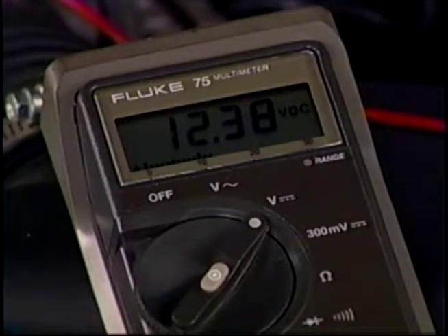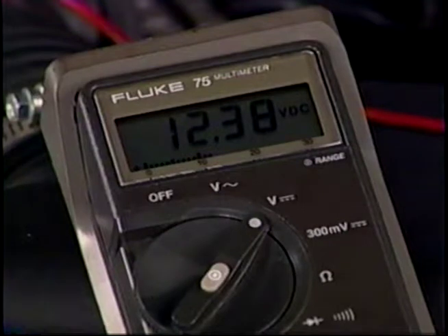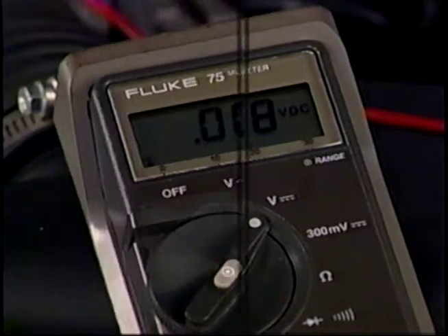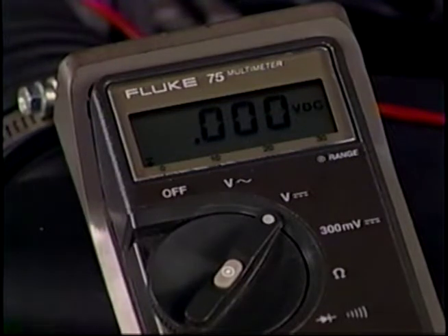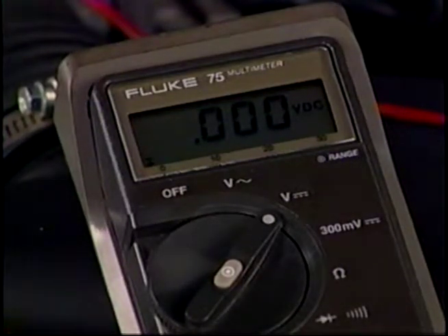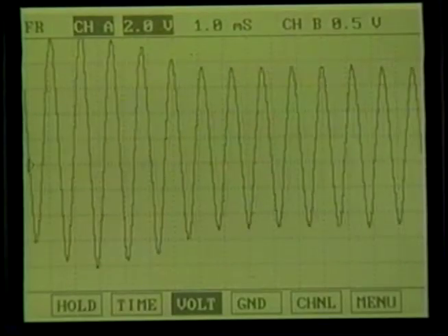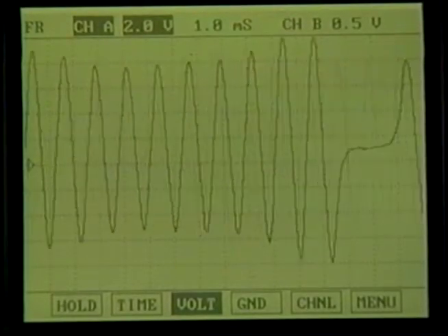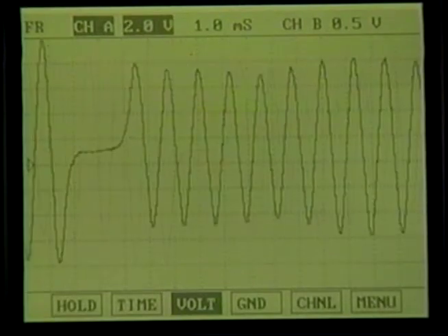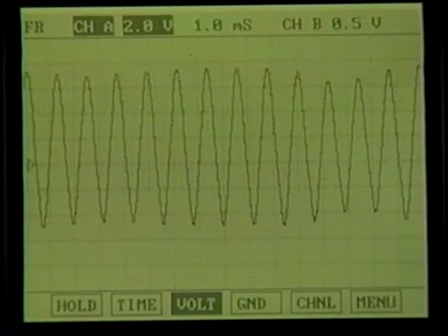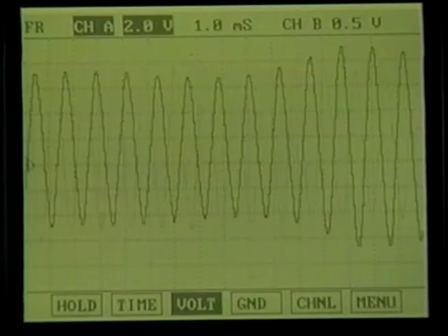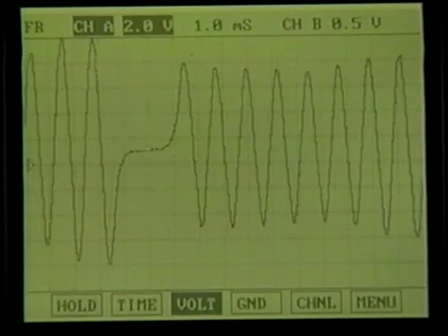If there is a failure of a position sensor or part, the trigger function will be lost. Shorted triggers will supply current to the switching transistor all the time and cause the coil to overheat before going open. Open triggers will leave the primary circuit open and no power flowing to the coil. A digital oscilloscope is the best tool to check the pattern on the triggering device, such as the crankshaft position sensor on an OBD2 vehicle. Misfires can occur if the sensor signal is intermittent.